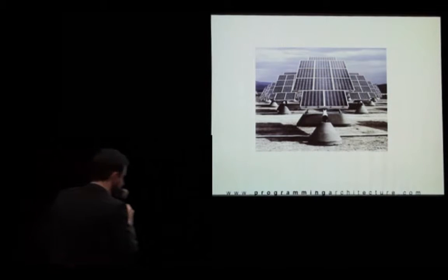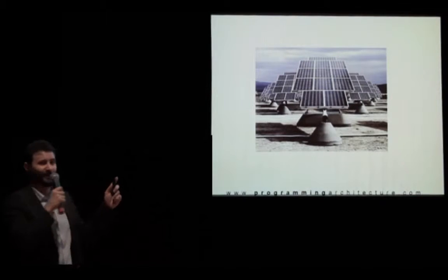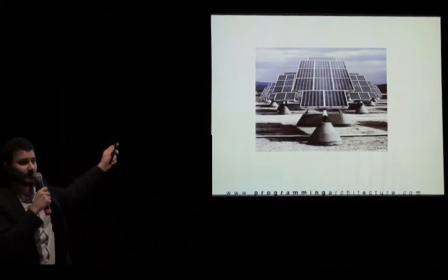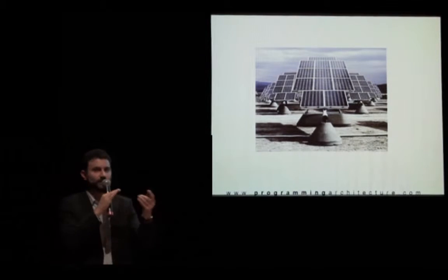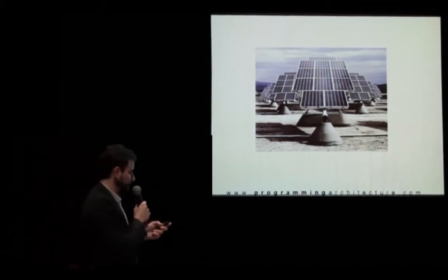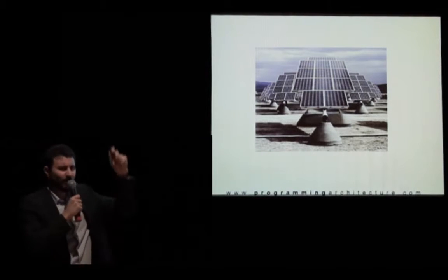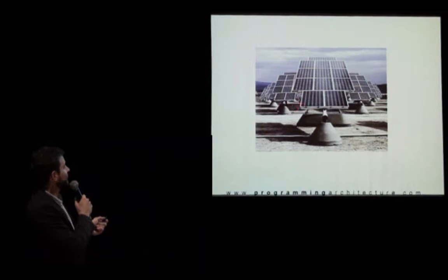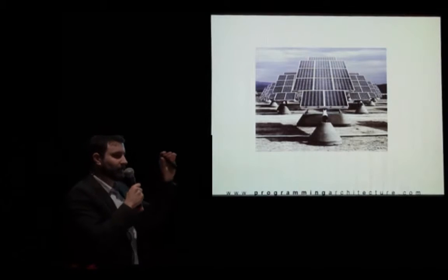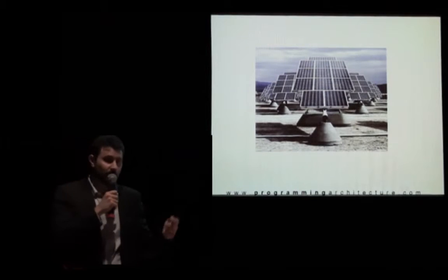But for this, I did a bit. For an electrical engineer company, I was actually hired to do shadow calculations for these solar trackers that follow the sun. And when you have these solar trackers, you cannot avoid shadow. They always throw shadow on each other. If you space them too much, then it's not efficient. So I had to calculate geometrically how it works, and I gave them kilometer-long Excel tables that for every little module like this, for every minute of the day, they got the calculation how much are they in the shadow and how much in the sun, in percentages.